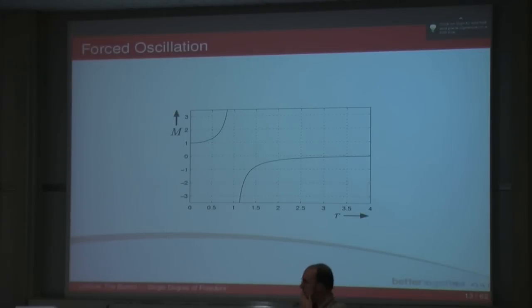And so if you were to plot amplitude over frequency, here m is normalized, so it is the amplitude over the static amplitude. Static amplitude is when omega is 0, so obviously I get 1. And this is the frequency ratio, omega divided by omega 0. Obviously when they're equal to each other, I get a value of 1. When omega is less than omega naught, I get a value between 0 and 1, and when it's greater, I get a value greater than 1. And you can see that up to the natural frequency, we have a positive amplitude that's heading towards infinity. I cross over 1 where amplitude is infinity, and I come back on the other side, coming from minus infinity and settling out at 0, the line connected to 0 on the y-axis. That proves what we've got going on.